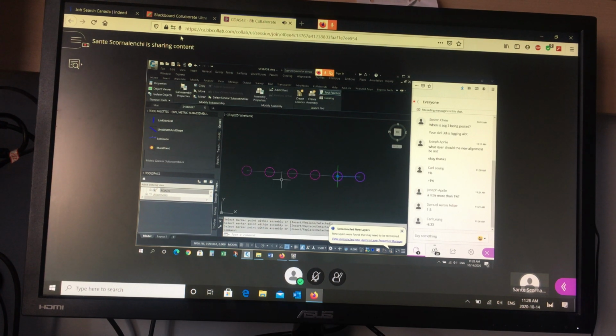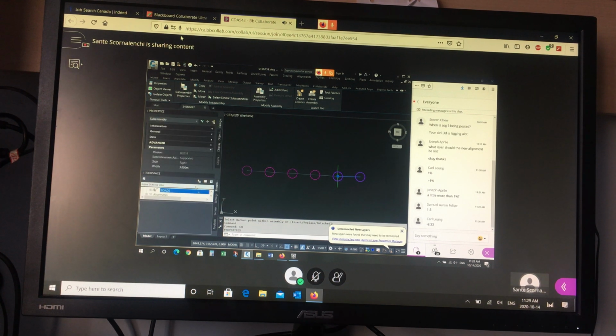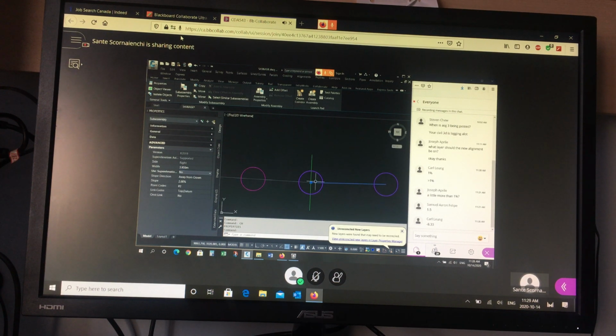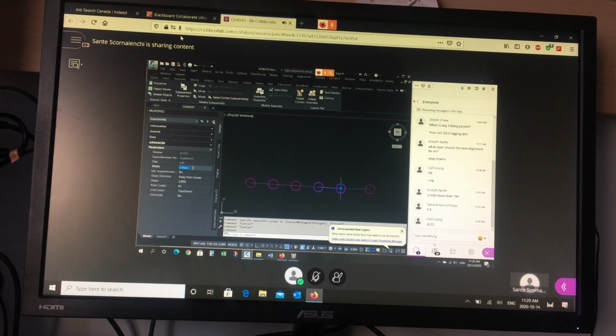Let's create this one. This one is going to be the pavement. So if I change the dimensions of that, it needs to be 3.95 wide, and it needs to go up at positive 2, so that's correct. Now let's do the left side. This is the gutter. I know the gutter is only 0.3 wide. Right? It's only 0.3 wide, and the slope is negative 8.3333.